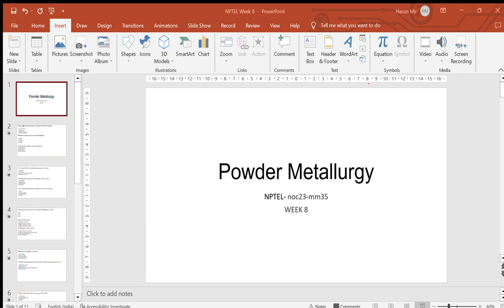If you heat an organic, polymeric chain, it will degrade into smaller chains, and these will be released in the form of gases, say CO2, H2O, depending on what kind of polymer you are using. And the solvent will try to dissolve the binder, because based on the principle of chemistry, like dissolves like. So you can use some organic solvent to dissolve your binder from the powder mixture. So both of these techniques can be used.